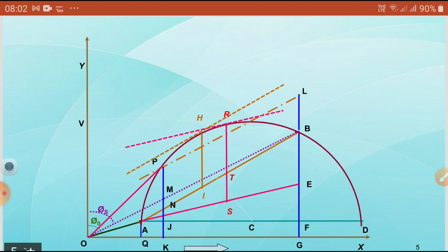Okay. So, a diagram giving the locus of the current drawn by the induction motor is referred to as a circle diagram. That means our aim is to know I1, the stator current. That is the current which is given to the motor, taken from the supply. This current magnitude and its power factor change based on the slip. That slip means the changing rotor speed. How does the rotor speed change?